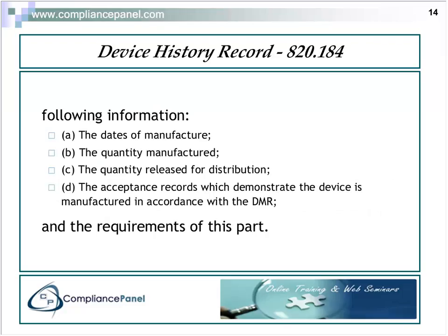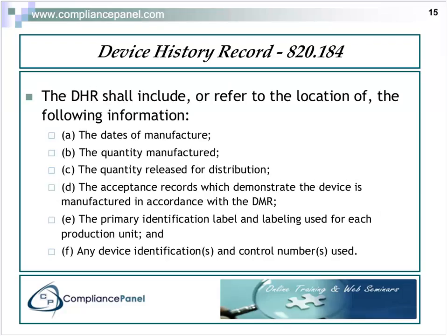One item that I didn't talk about that people are using a lot of during the manufacturing process, and it's relevant to your device history record, is if you're using things like Access databases to capture data or Excel spreadsheets to perform calculations for you, somewhere along the line you have to show that those were properly validated by yourself, because Microsoft is never going to claim that any of their software has been validated for use on or with a medical device.